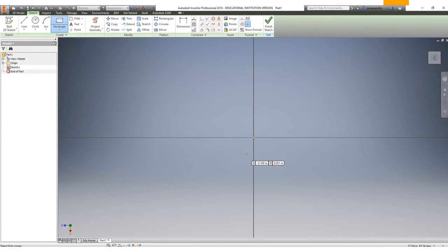And now I'm going to come right here on that y-axis center point, and you'll see the dot turns green, it snaps on there. Okay, so I'm going to click right on that center point, and then I'll make a rectangle, and as I pull it out, something very similar again to AutoCAD, is that we can choose the sizes, and this is going to be very important in this section, that we want everything to be precise.